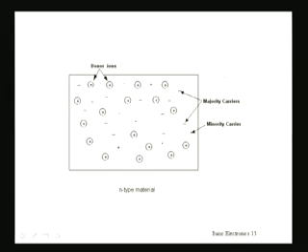So one atom of this extrinsic semiconductor, when it donated one electron, has become an ion having one positive charge, which is shown here. So the donor ions are having one positive charge, and there will be electrons which are in abundance in the n-type material. These are called majority carriers.